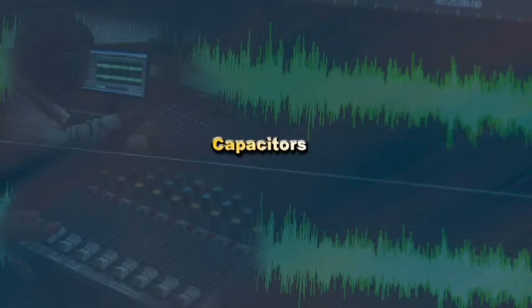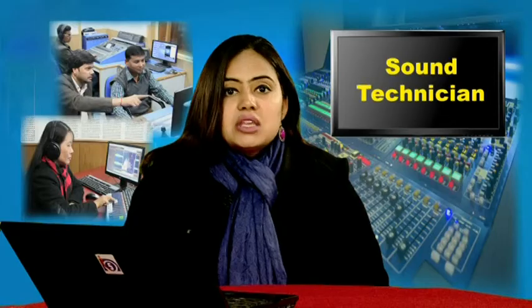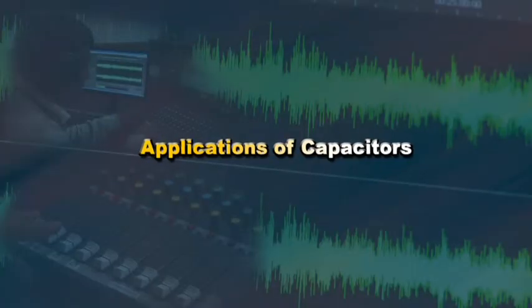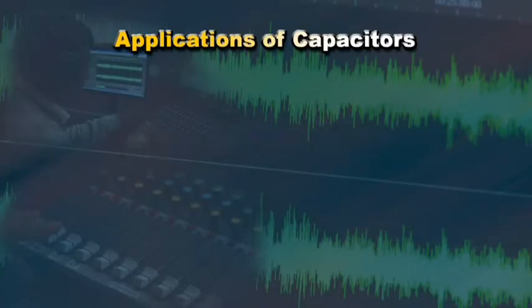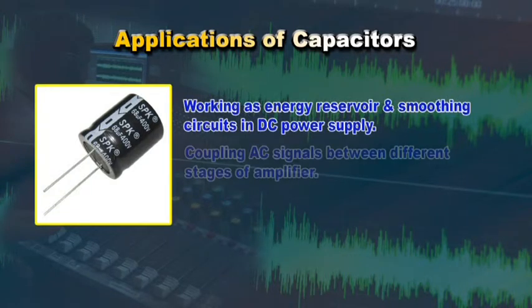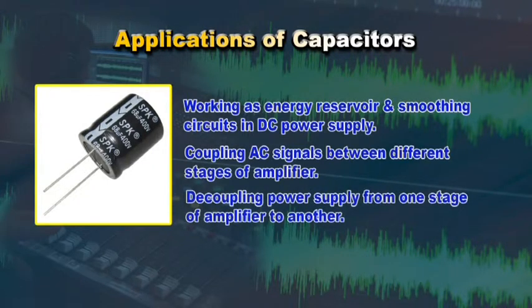Now let's talk about capacitors. Capacitors are passive components which store energy in an electrical field. These components do not dissipate energy like resistors. Typical applications of capacitors include working as an energy reservoir and smoothing circuits in DC power supply, coupling AC signals between different stages of an amplifier, and decoupling power supply from one stage of an amplifier to another.